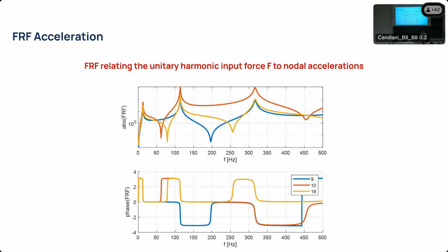So in this case, we can compute displacement against force for each frequency. We can plot acceleration against force for each of the various frequencies, and then you're able to get a quantitative response of your structure.